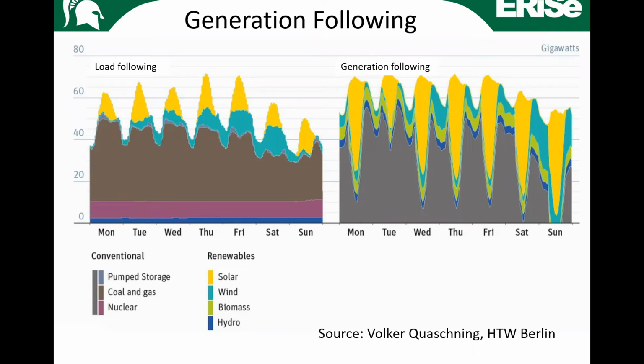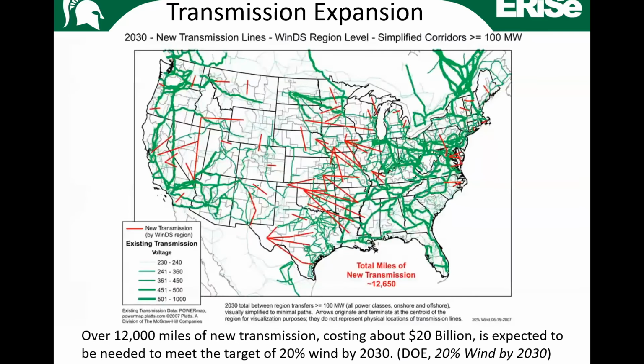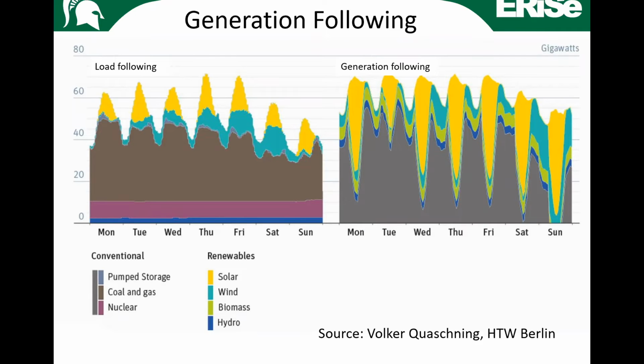See the envelope of these curves, this resembles the daily variation of load that you've noticed, right? So this is indeed the total load as it varies throughout the day over, say, a span of 1 week, okay? And what we do in power systems today, in the grid today, is load following. That is, people are allowed to switch their loads on and off at will, and we have set up controls that allow the generators to track this load.